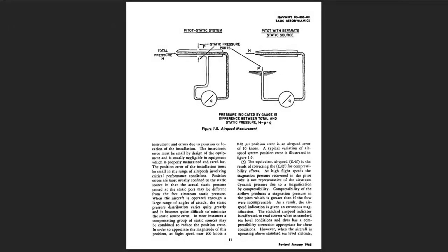Actually, there can be many conditions of flight where the airspeed indicator does not truly reflect the actual velocity through the air mass. The corrections that must be applied are many, and listed in sequence below. 1. The indicated airspeed, IAS, is the actual instrument indication for some given flight condition. Factors such as an altitude other than standard sea level, errors of the instrument and errors due to the installation, compressibility, etc. may create great variance between this instrument indication and the actual flight speed.